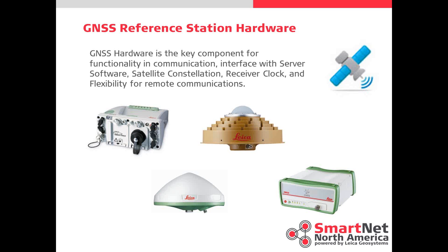And one of those components, of course, is the reference station. With the reference station, you want it to be a very low noise floor reference station. You want to have a high quality antenna that's very stable, that's resistant to multipath, because all we're always doing in GPS is trying to fight noise. And if we start with a noisy element at the receiver or the antenna, then by the time we get it out to RTK broadcast, we're going to have noise in the system that we have to fight through, which is what we want to get rid of.